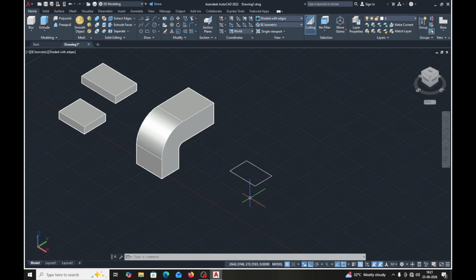If I make the direction on the XY plane, extrusion will not take place. So for this, I will first have to change this. Now the XY plane is vertical, and the Z axis is horizontal. Click ortho off. You give any length, suppose 200. Tab key, angle, suppose 50 degrees. Enter, out of the command.